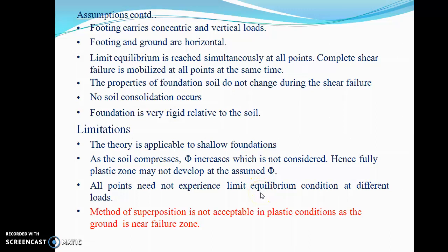Okay, rigidity is much higher relative to soil. The limitations of this theory: first, the theory is applicable only to shallow foundation. As the soil compresses, phi increases. This is what I just spoke about, but we don't give that advantage. Okay, so we are giving slightly conservative results. Hence, fully plastic zone may not develop at the assumed phi.